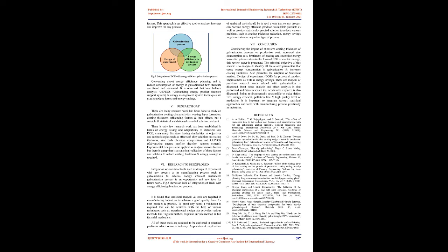B. Effect analysis. A comprehensive study of root cause analysis regarding excess coating thickness provides its effects on the galvanization process and product parameters. These effects are mentioned here in terms of cost, quality, and energy. Quality of end product is affected by thick coating, which causes brittleness, which is unacceptable to customers. Rejection by customers causes need of rework, which creates an obstacle in the smooth flow of the production process. Cost, increase in production cost, zinc consumption cost, due to excess zinc coating. There is dross formation in the zinc pot, which occurs due to various chemical reactions.